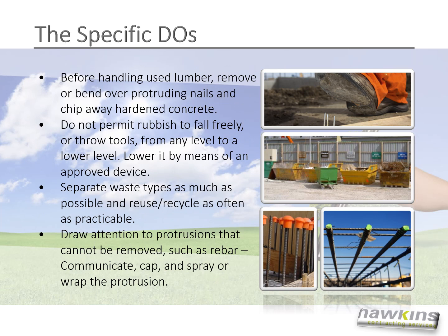Before handling used lumber, remove or bend over protruding nails and chip away hardened concrete. Do not permit rubbish to fall freely or throw tools from any level to a lower level. Lower it by means of an approved device. Separate waste types as much as possible and reuse or recycle as often as practicable.